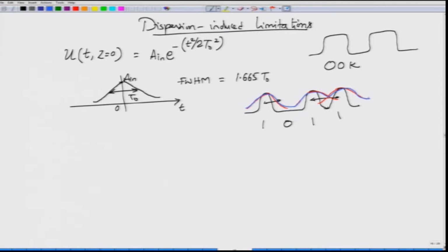This is also getting influenced because if you, for example, have a threshold somewhere here, then you can see that because of the pulse spreading from the previous slot and the pulse spreading from the next slot, the overall amplitude is increased when the bit is 0. So, sometimes if this pulse envelope reaches above the threshold, then even this bit will be in error. In fact, you normally model the inter-symbol interference by a certain memory length, indicating that the previous m slots to the next m slots are the ones which are interfering in the present slot.